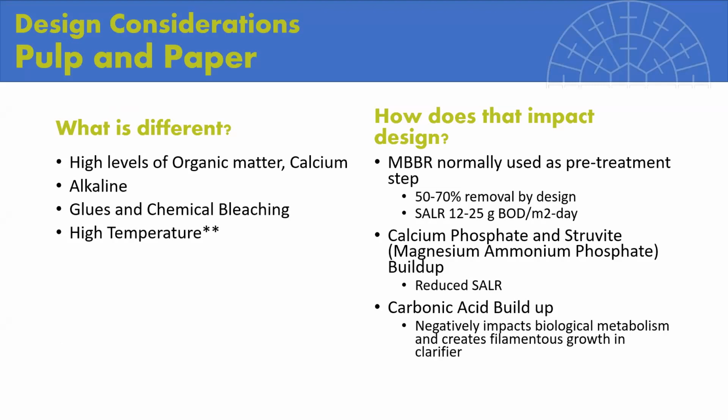As the plants grow, so does the liquid consumption, or wastewater generation. The flow rates tend to increase. BOD or COD may increase. But more recently, what's happened is regulatory pressure, and you find a more stringent effluent required. Most of what I've seen from personal experience is MBBR used as a pre-treatment step, because a lot of these systems already have large clarifiers or large activated sludge plants, since they've been around for a long time. So MBBR is added as a space-efficient way to provide roughing or pre-treatment for BOD and COD.